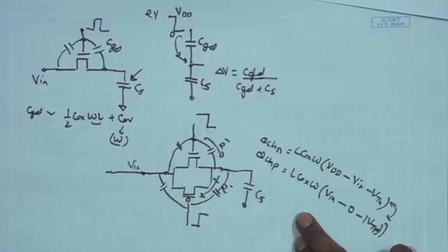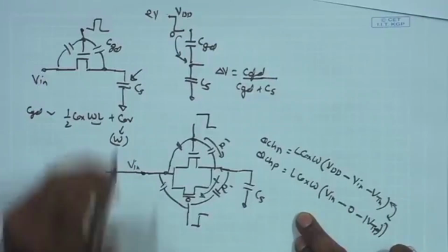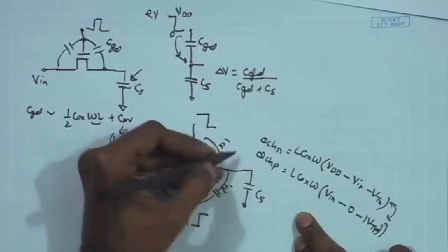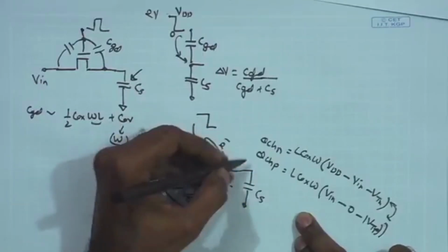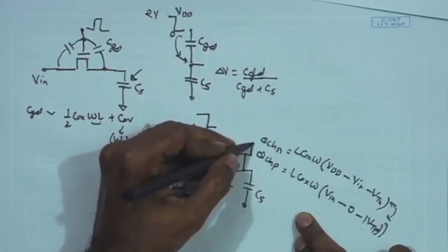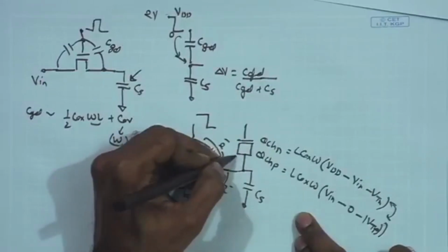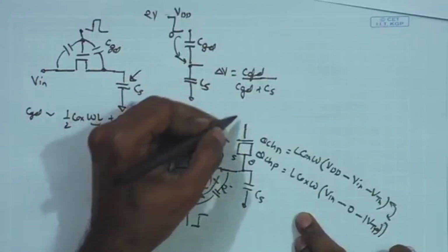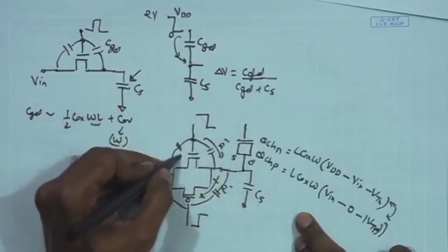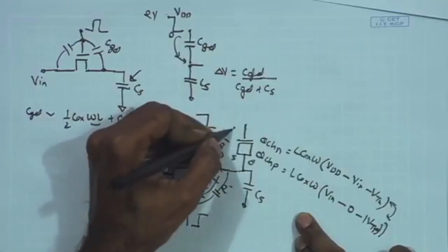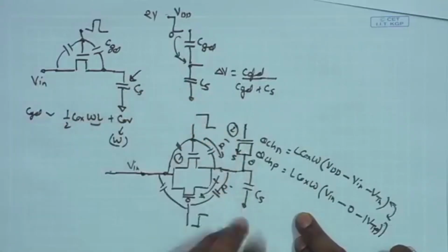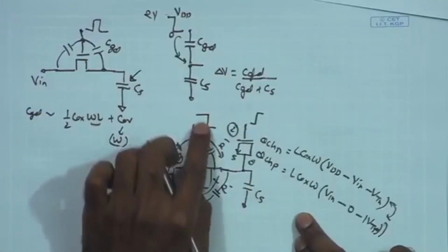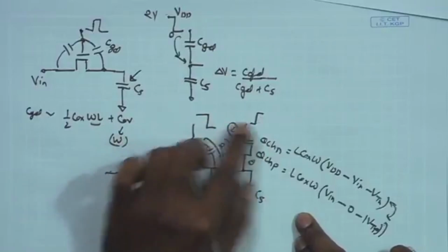There are other schemes people do apply, like rather than depending on this NMOS and PMOS pair, you also add additional dummy transistors over here. For example, for the NMOS, you add a dummy transistor whose source and drain are shorted together, and assume that this W is half of the NMOS over here. So, if this is M1, this is M2. What I am doing is shorting the source and drain, and this is the gate. I am applying just a clock bar over here. So, when this turns on, this turns off, this turns on.